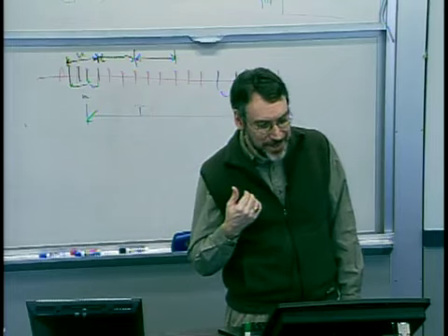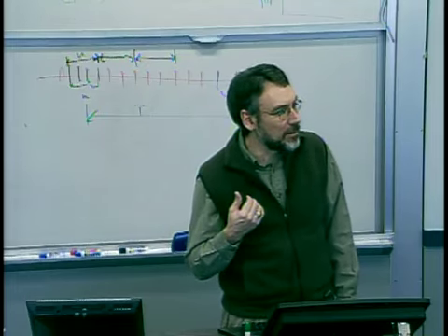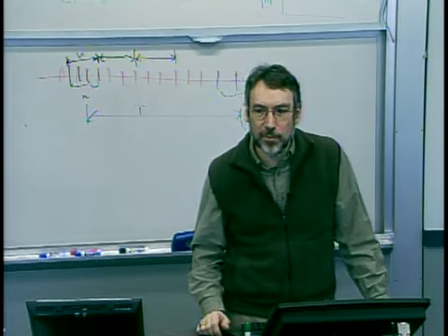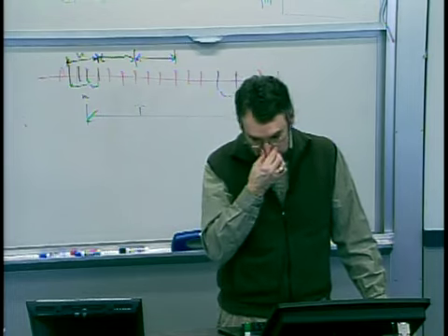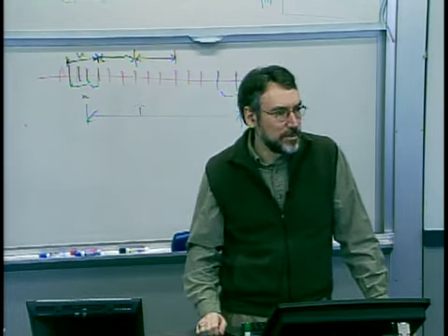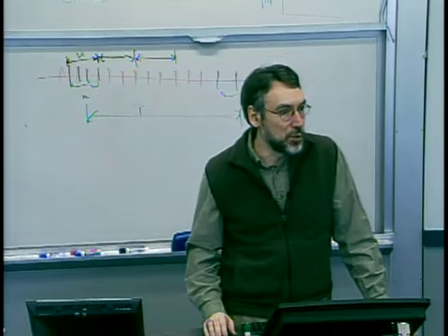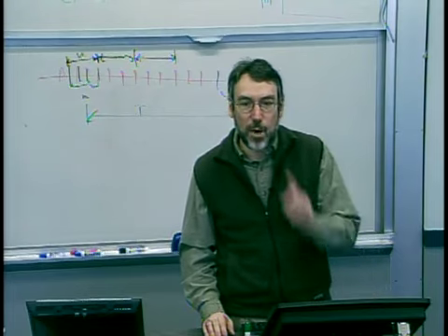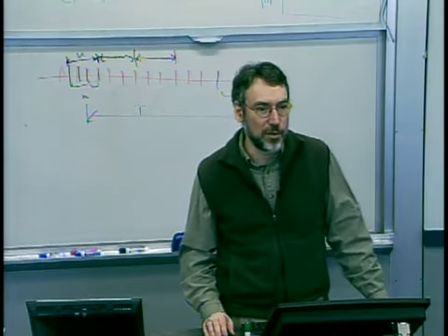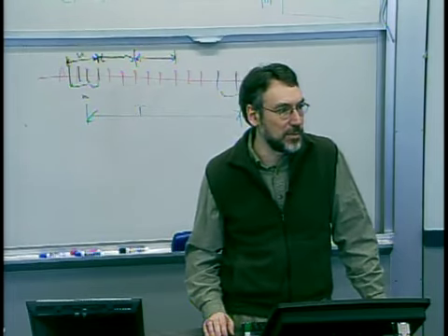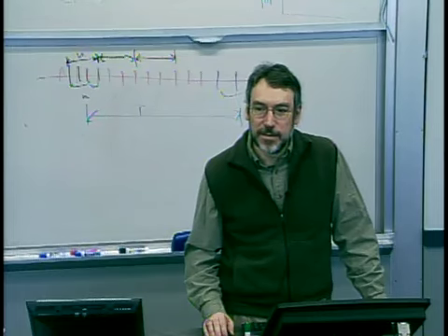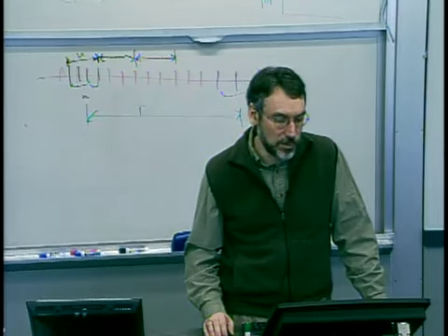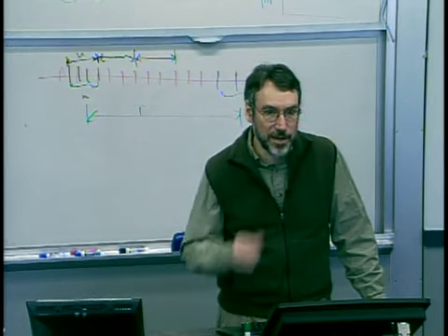If you were just eyeballing it, what do you think a Cp or a Cpk would be for this process? I have no idea. I haven't done the calculation. You could go and do the calculation, right, based on what? What would you do to actually formally try to calculate a Cp or a Cpk for this process? Standard deviation. Yeah, you'd calculate the mean and the standard deviation.